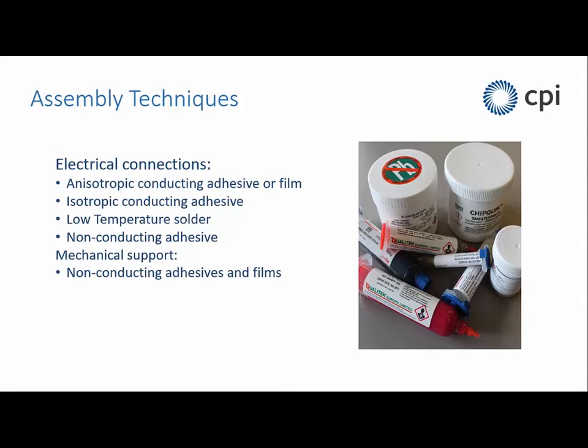And you can process up to about 180, I think, for that. Polyimide is a nice material. That will really allow us to go up to 300 degrees processing if we want to. So for that, we can use conventional solder. But that has a problem of cost. It's a very high cost material compared to PET or PEN. So low temperature processing is an important part of electronics and printable assemblies.